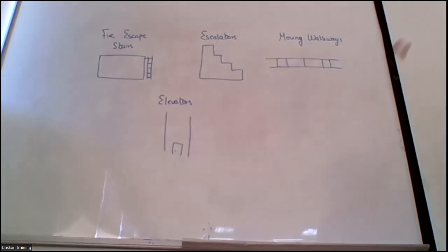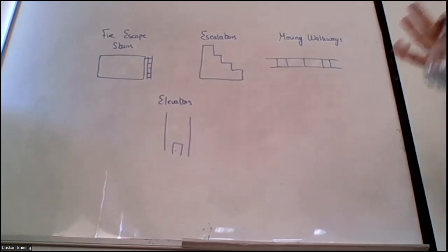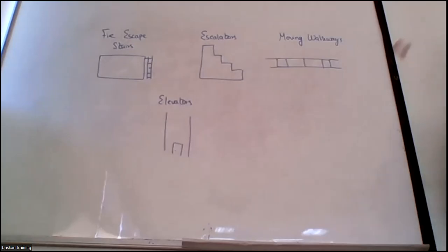Fire lifts are still not considered as means of egress. For us, it's not. If firefighters want to use it, they can use it. For us, it is not a means of egress. We cannot escape from there. Firefighters' elevators are only for firefighters if they want to use them for escape. For us, we cannot use it. So these are components which are not considered as means of egress.